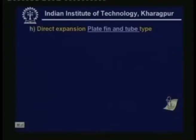Next, let us look at the direct expansion plate fin and tube type evaporator. As the name implies, the plate fin and tube type evaporator is constructionally similar to the plate fin and tube type condenser. So here the external fluid is air. In the case of the condenser also, the external fluid is air and the refrigerant flows through the tubes. In the plate fin and tube type evaporator also, the refrigerant flows through the tubes while the air flows outside the tubes.